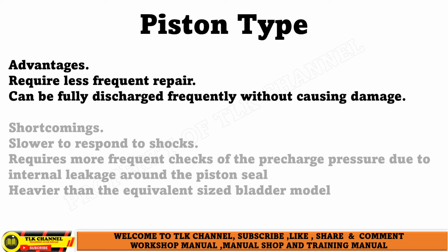Piston type. Advantages. Require less frequent repair. Can be fully discharged frequently without causing damage. Shortcomings. Slower to respond to shocks. Requires more frequent checks of the pre-charge pressure due to internal leakage around the piston seal. Heavier than the equivalent-sized bladder model.